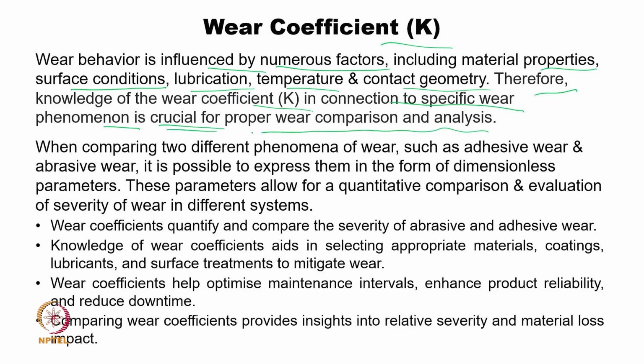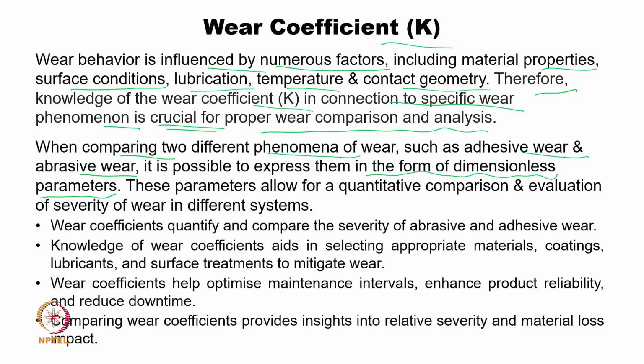So, wear coefficient is very essential when we want to compare different materials, different lubricants, maybe different situations, different temperatures, different hardnesses. When we are comparing two different wear phenomena, such as adhesive wear and abrasive wear, it is possible to express them in dimensionless form. That is why, for comparison and evaluation of different materials, or to understand the severity of wear in different systems, wear coefficient is very important. So, I have written 4 bullet points.